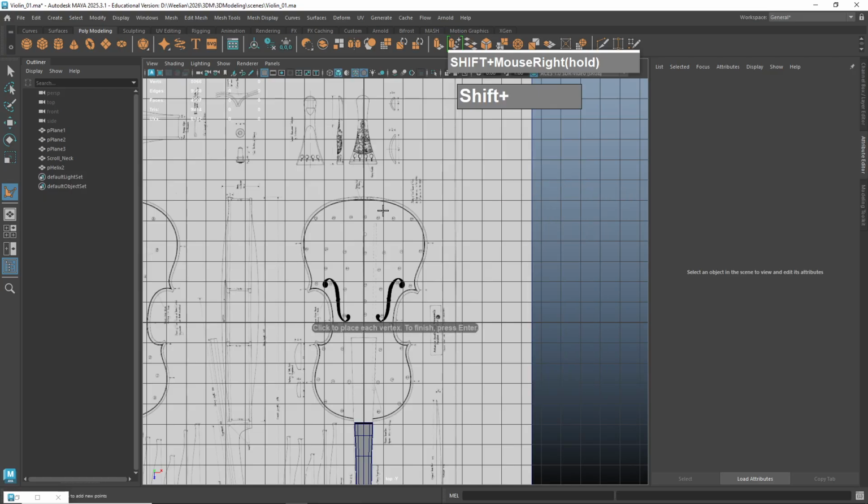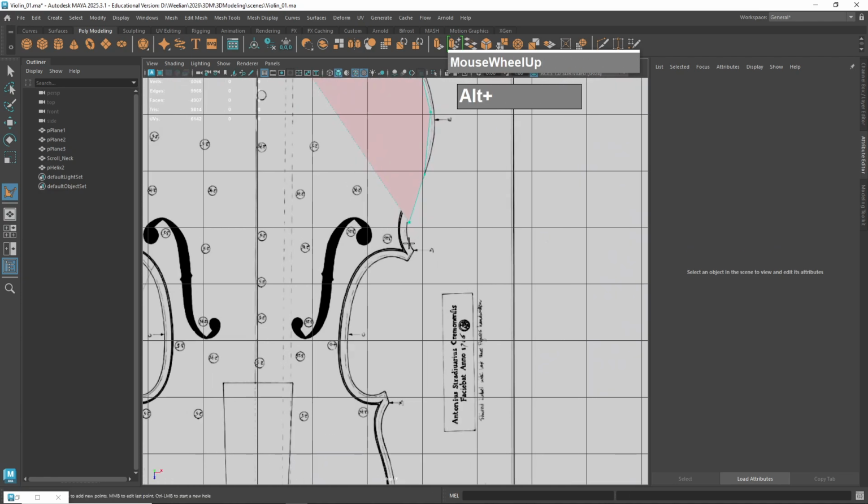So I'll go to the create polygon tool and start by drawing one in the center here, and the second one, just going to use the grids to help me spread out the number of vertices that I need to click on. So now when I come out to this area here, I just have to use a little bit more detail.